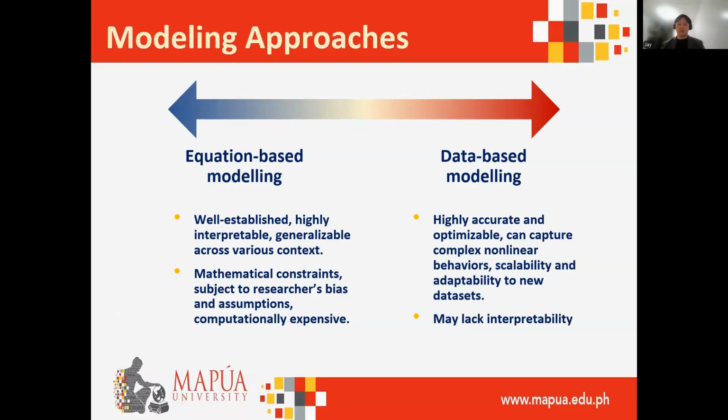But one skepticism towards ML models or the data-based modeling approaches is that they may lack interpretability and their results might not directly translate to physical phenomena occurring inside the fuel cell. However, using algorithms to explain the ML models through measures such as Shapley values can help in determining how predictors influence the variability of the performance and durability of PEMFC.